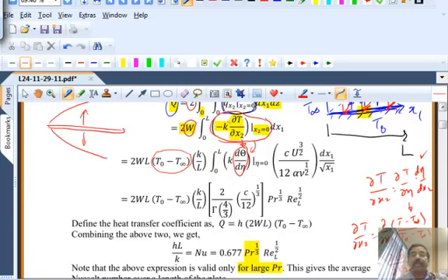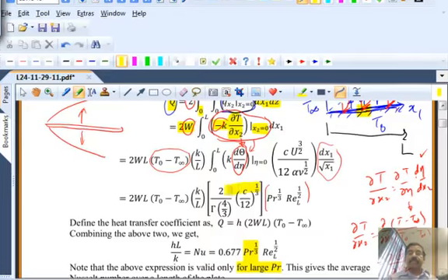So those are exactly the same expressions after you have taken out this T0 minus T infinity. Okay? And then the k comes out there, and the L will come out when you do the non-dimensionalization of x1. Okay, and that's all you need to do. Then carry out the simple integration with respect to x1 of this. Everything else is a constant, and put it in dimensionless form. You get this result. Notice here, this whole thing is a constant.